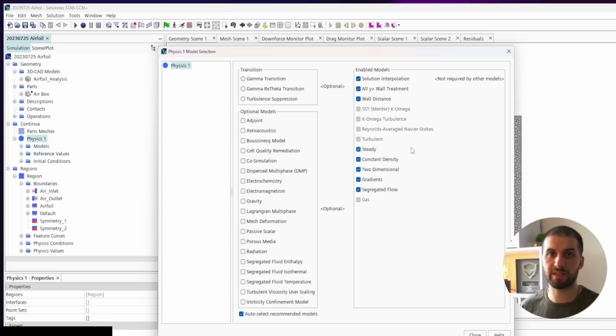If you might have seen some of the CFD podcasts on this channel, you might notice that almost all CFD experts always say, take your problem, simplify it to the most simple model that you could choose, and increase the complexity step by step. Then if you increase the complexity by a little bit and tweak one more parameter, but the outcome is garbage, you can debug it very easily, saying this specific tuning of my model actually caused the simulation output to be garbage. So I can go one step back and rethink the parameter that I've tweaked. Okay.